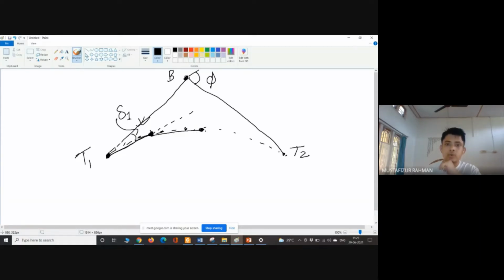And then say for example, the next is another 20 meter from this point. Okay, so now how much is it deflecting? So this deflection is here, small delta 2. So you go in this direction 20 meter. The direction is given by the angle delta 2, and we get the second point on the curve, right?